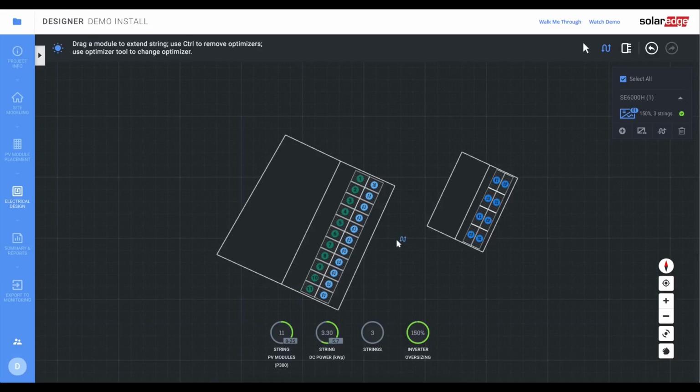And this is really cool actually. When they do the install, there's little QR codes on the back of each of the optimizers, and they can basically take these little stickers off with those QR codes and put them on a paper map that they then can easily just scan in to give you, at the end of the installation, an equivalent active version of this map. So there's a monitoring feature in the SolarEdge software that will basically tell me how each of these panels and the optimizers are performing. So it's really good to identify faults and quick remedy, that kind of thing.